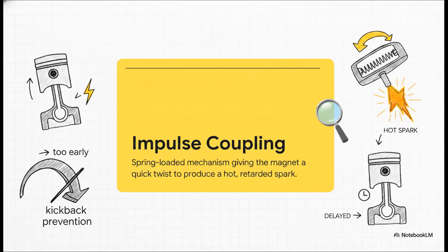But here is a classic mechanics dilemma. When you're just starting an engine, it's turning really, really slowly. A slow-turning magneto creates a pretty weak spark. And worse, if it fires too early, the piston will violently kick back in the exact opposite direction. Definitely not what you want.